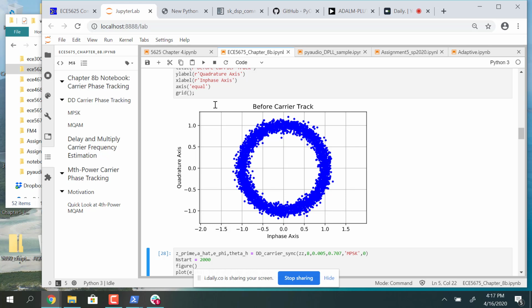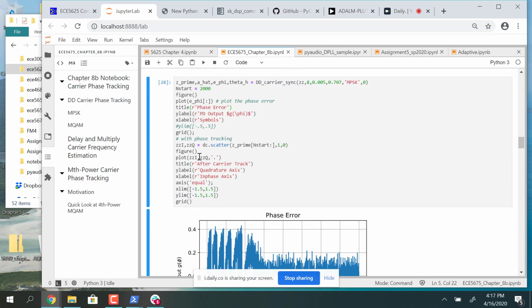How many bits of information can that carry per phase value? Log base 2 of 8 is what? 3? So we have 3 bits per symbol in this system of digital modulation.